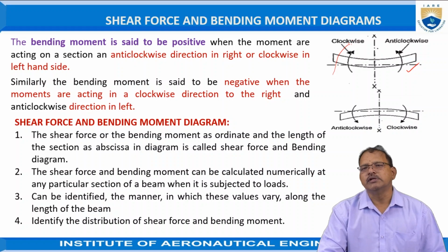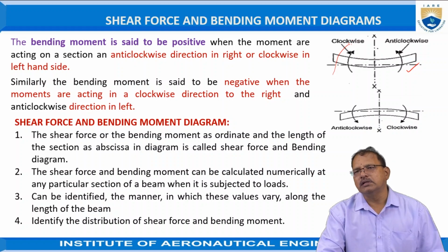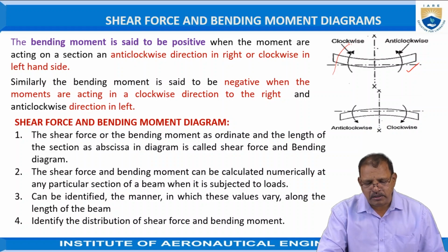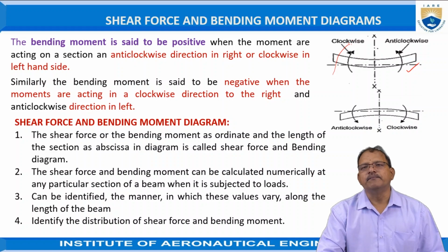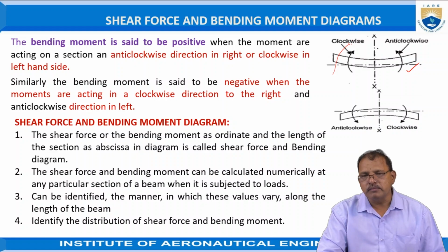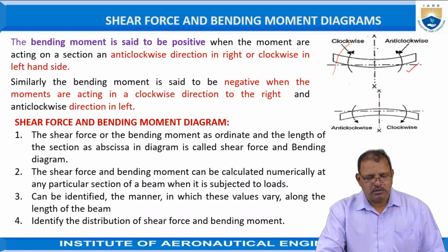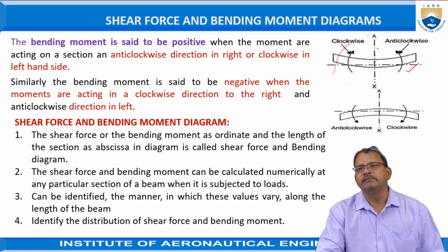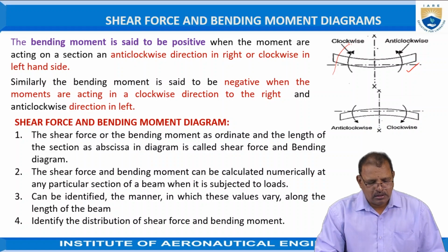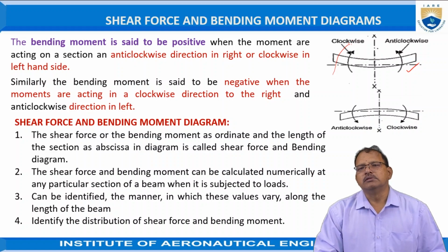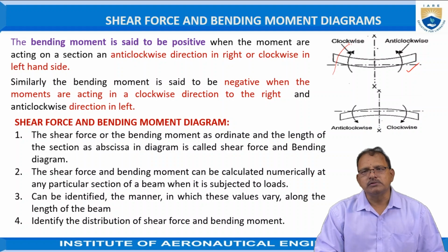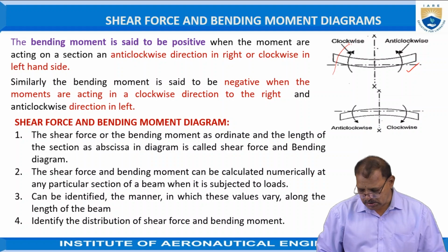The diagram showing the bending moment versus the length of the beam is known as the bending moment diagram. Similarly, shear force versus the length of the beam is the shear force diagram. The shear force and bending moment can be calculated numerically at any given point when the beam is subjected to loads by using these diagrams. These diagrams give us the distribution of shear force as well as bending moment across the section of the beam.